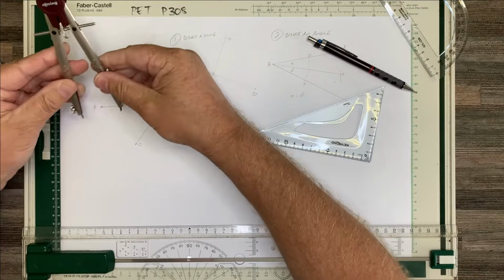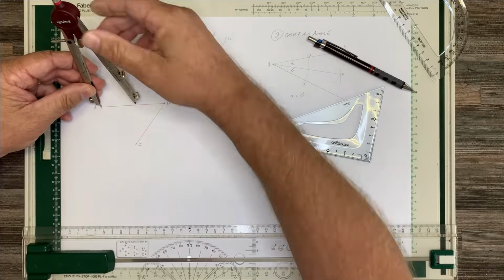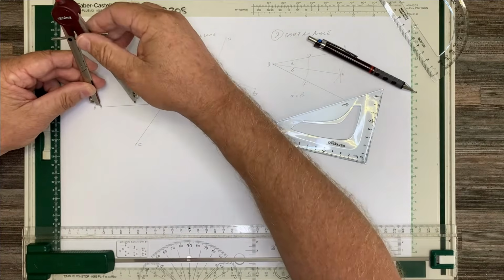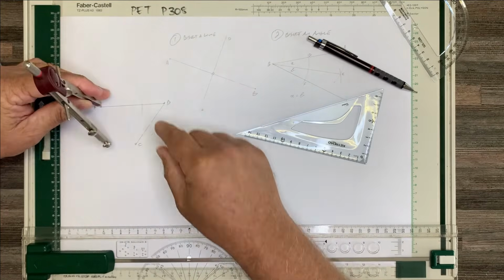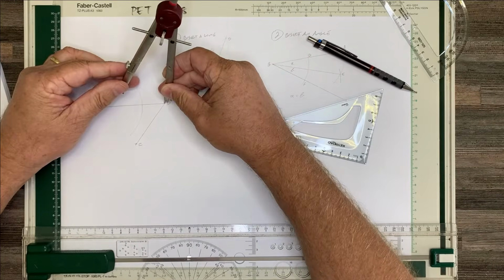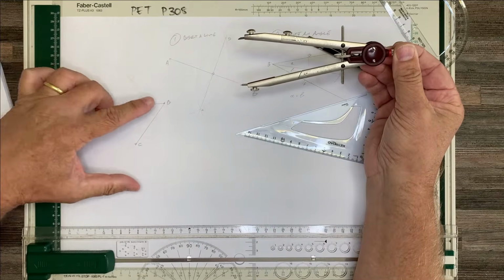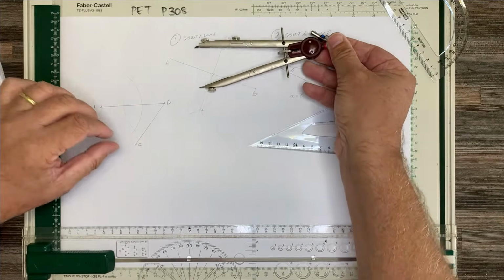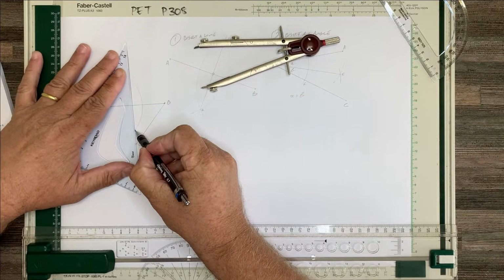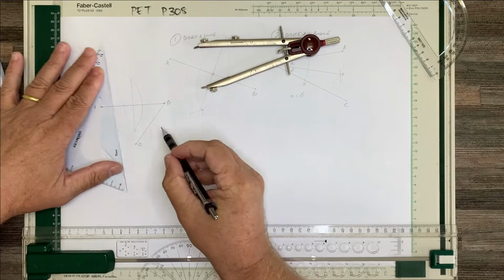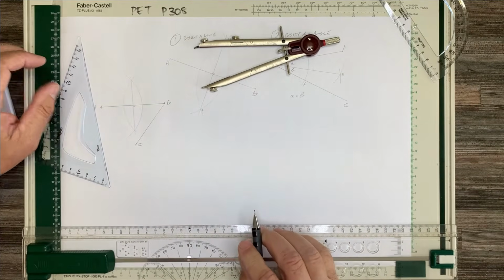So to do that, we are going to draw a perpendicular line that bisects A and B. So it's very similar to what we did when we bisected a line. We'll draw an arc from both sides with our compass set to a radius that is just greater than halfway. All right, so now we've got 2 intersection points which will give us a line that bisects and is 90 degrees actually to AB.